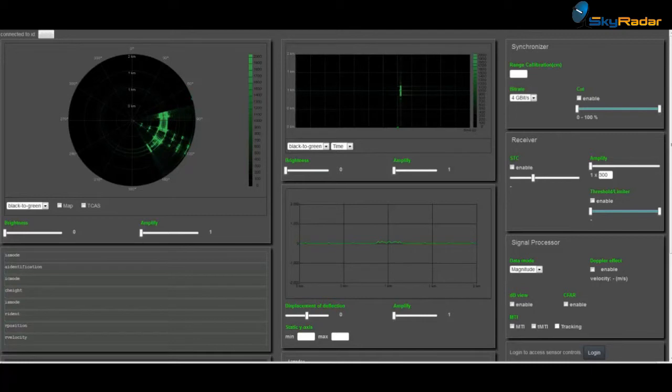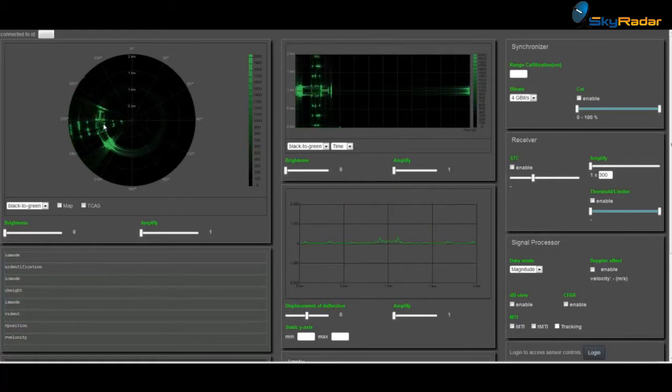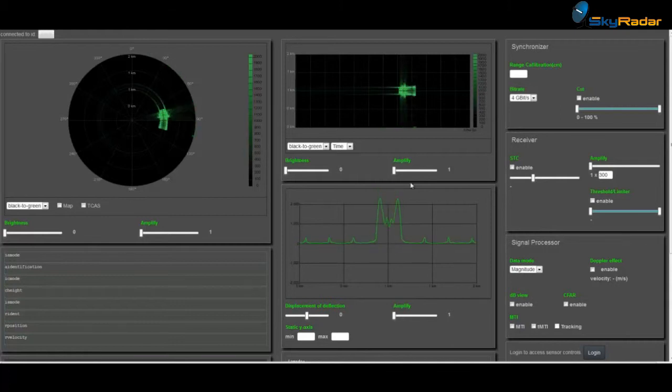iSAR and SAR offer different variations of measuring cross-sections of aircraft. You see here how the A-scope comes up, now the B-scope. And the PPI doesn't give such a good view as the B-scope for a cross-section. We got a second rotation. Soon we should see it in the B-scope again, in the A-scope and in the B-scope. The aircraft comes up now here. Beautiful cross-section.